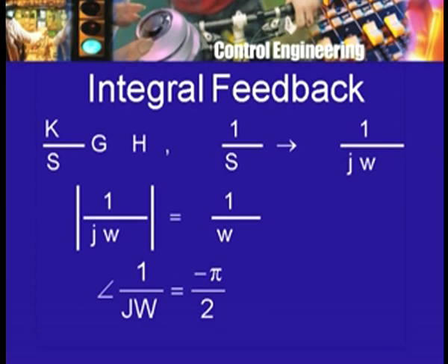So, in other words, the loop transfer function gain at very low frequencies is going to be very large. It is not going to be some finite constant. In fact, it is going to increase as you approach 0 from above. That is, as omega tends to 0, you consider smaller and smaller frequencies, the gain will be greater and greater. So, that was one mistake.